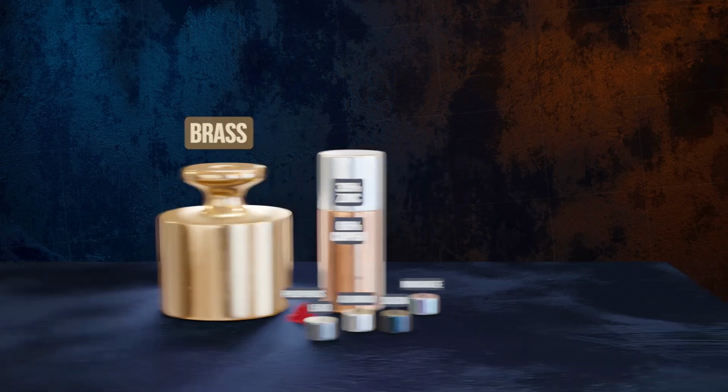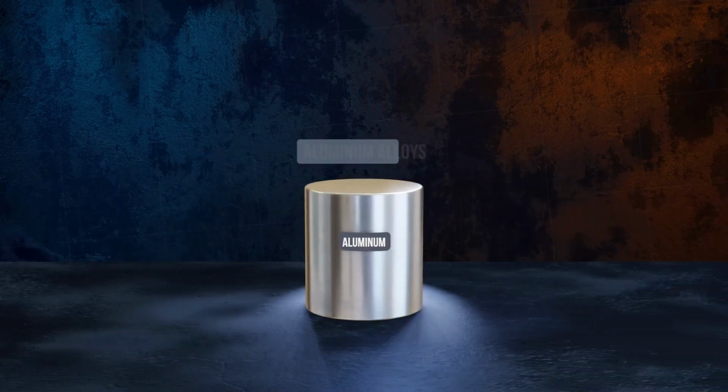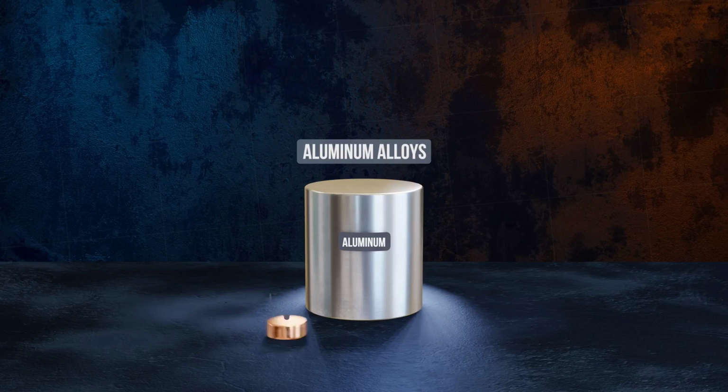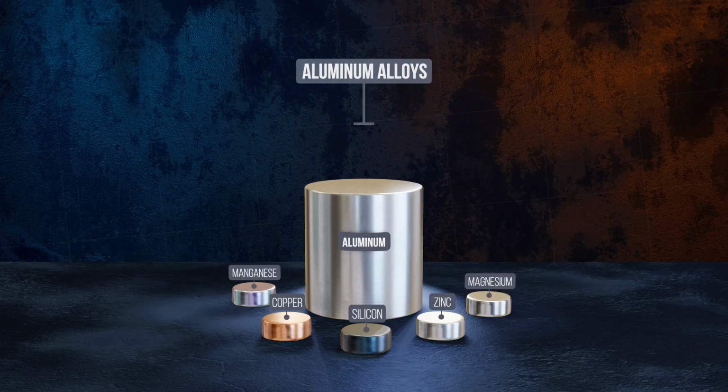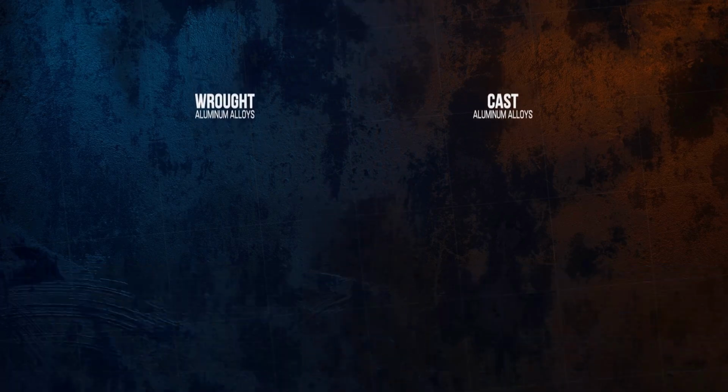Aluminum alloys are important in engineering and are often used for the good strength properties they provide at a light weight and reasonable cost. Common alloying elements are copper, manganese, silicon, zinc, and magnesium. Aluminum alloys are classified according to whether they're designed to be used for casting or to be worked, and are designated using specific numbering systems.